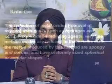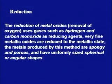Now, the second process is the process of reduction. So, what is this reduction? Reduction, as any student of chemistry knows, is the reduction of metal oxide, the removal of oxygen, using gases such as hydrogen and carbon monoxide as reducing agents. Very fine metallic oxides are reduced to metallic state. The metals produced by this method are spongy and porous and have uniformly sized spherical or angular shapes.